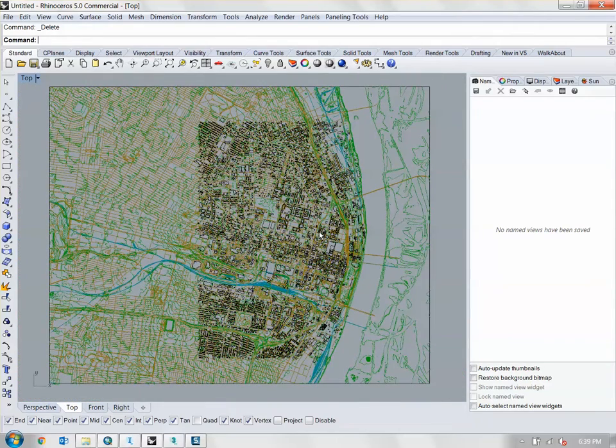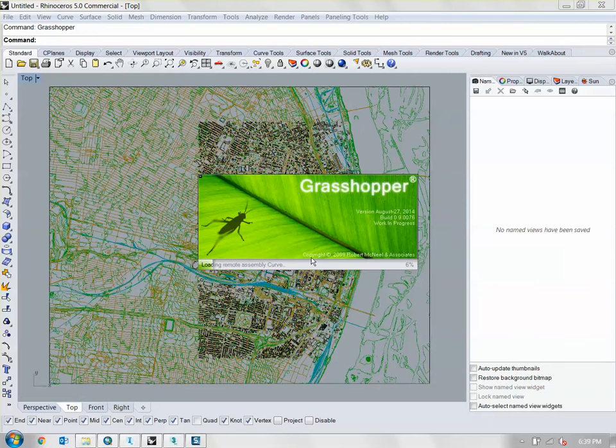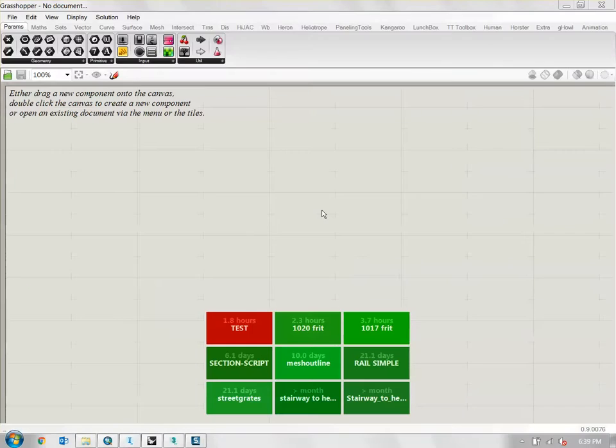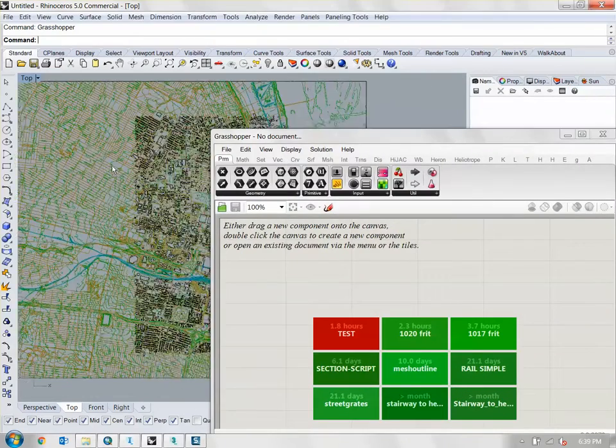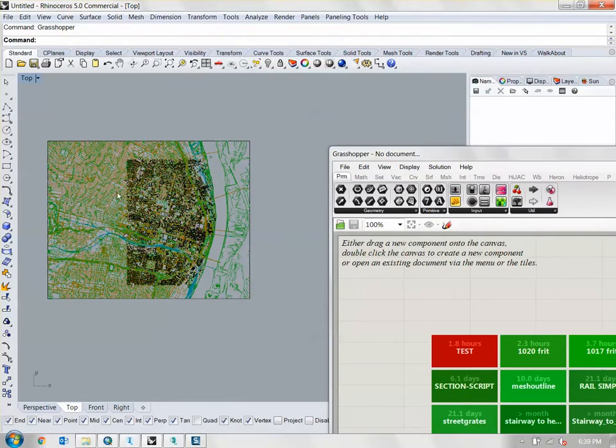So what we need to do is set up what's known as a translation vector. You don't want to move it to 0, 0, 0 and forget the translation units. You want to remember those units. I'm going to use Grasshopper, and you don't have to use Grasshopper for this, but I use this technique just because I want my translation vector to be a nice even number.